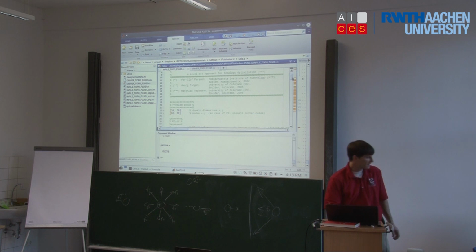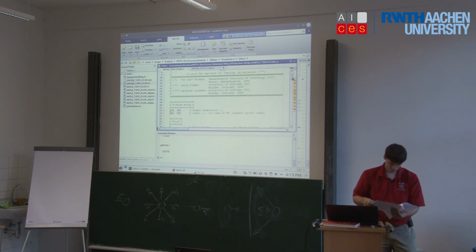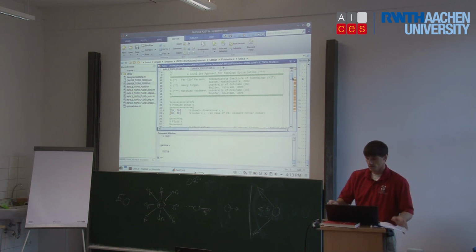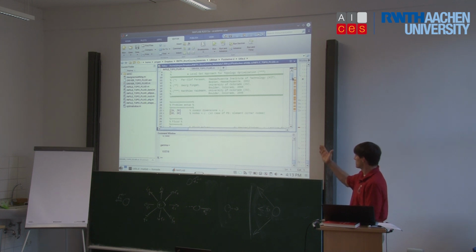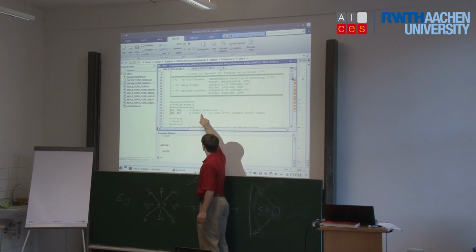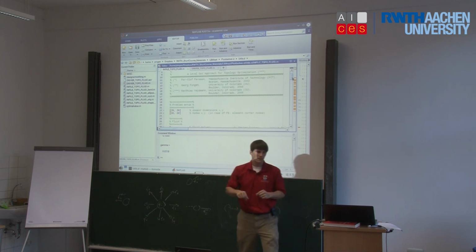Okay. And so there's some basic settings, and I'm going to decrease this just for the sake of time. Okay, so the basic drag optimization problem that we've been dealing with, I've solved with these settings. So we solved it on a domain, the size domain. So this is the lattice Boltzmann mesh. This is the level set mesh. What it actually ends up doing is we have one design variable in between.